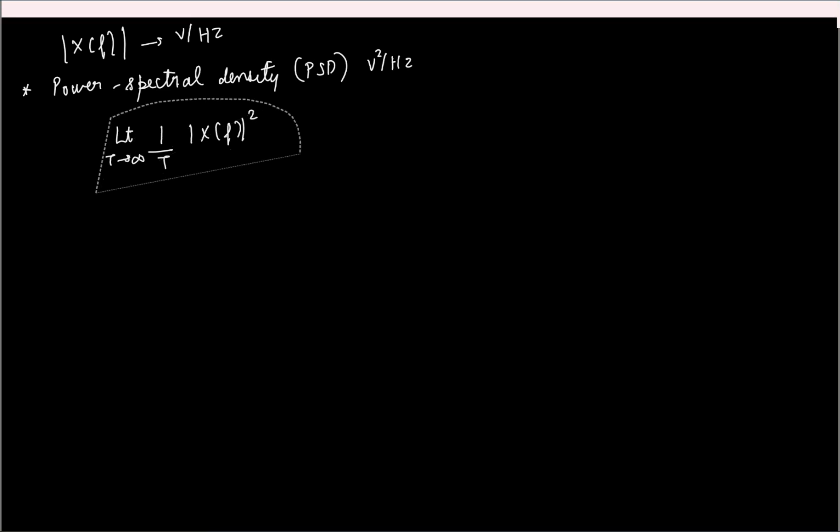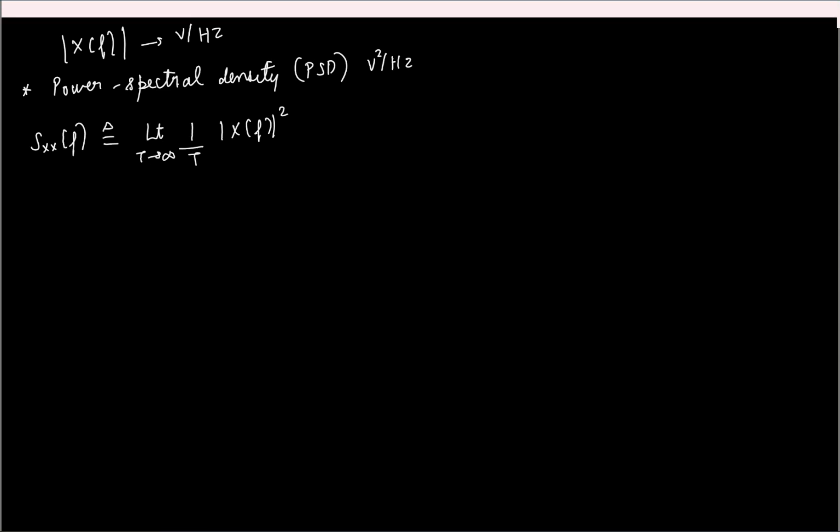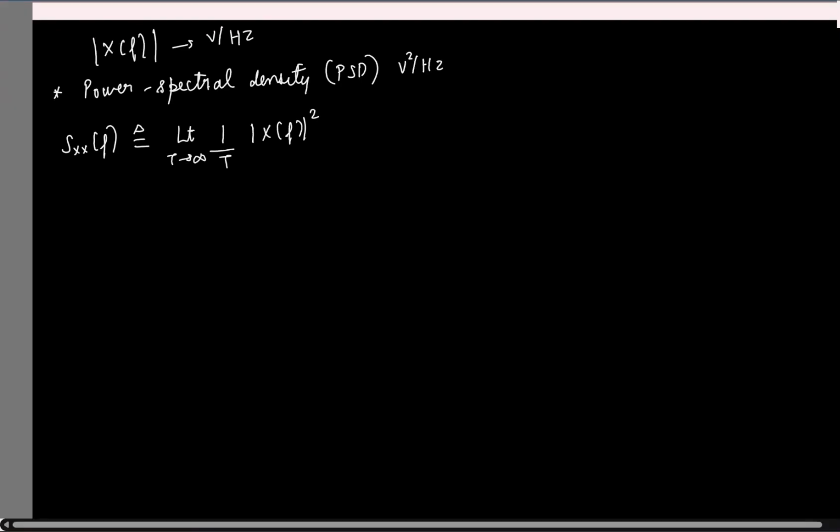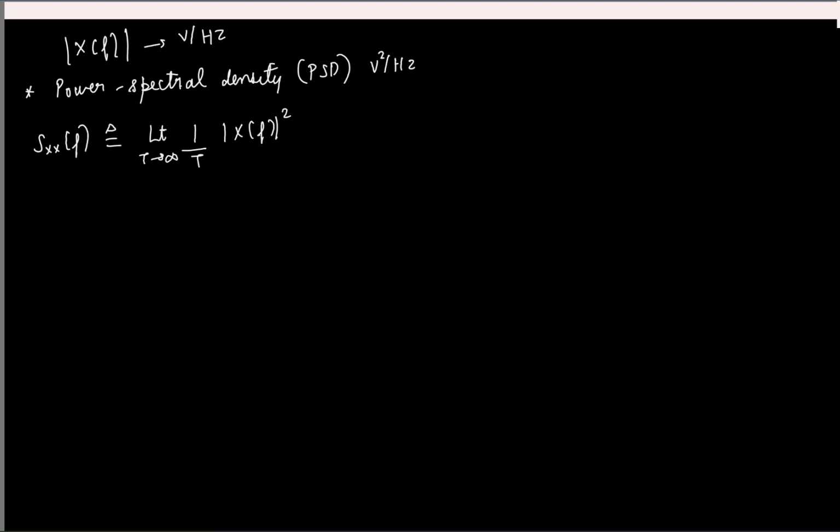So this is the definition of power spectral density, right? Again, just like your Fourier transform, it is a density function. So unless you have impulses in the spectrum, you cannot say that the signal has sinusoids at frequencies. Okay. So again, the physical intuition to understand this is, say you take a signal x of t, pass it through an ideal bandpass filter, say with a center frequency f0 and a bandwidth of 1 Hz, and then you take the power of the output signal, that will give the power spectral density at what frequency? F naught. It's again the power around a particular frequency in a 1 Hertz bandwidth. Okay.